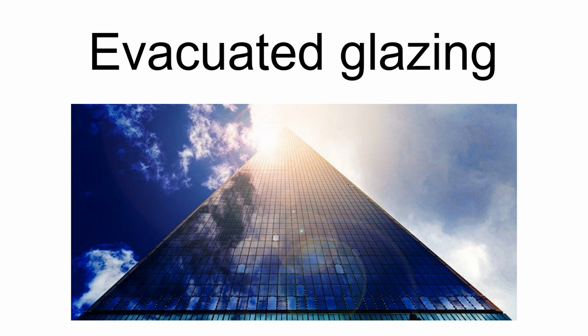The high temperatures necessary for outgassing also tend to destroy the highly effective soft low-emissivity coatings that are often applied to one or both of the internal surfaces, i.e. the ones facing the air gap, of other forms of modern insulative glazing, in order to prevent loss of heat through infrared radiation. Slightly less effective hard coatings are still suitable for evacuated glazing, however.